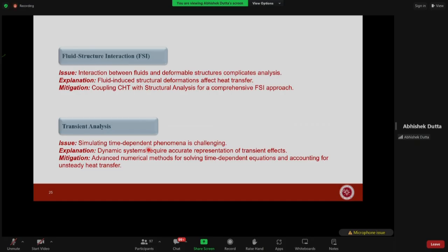The transient heat analysis. Yeah, this is also very important because most of the time our heat transfer solutions are steady state, and actually that is not accurate. So to avoid the mistake, we need to change to a time-dependent solution. And time-dependent solutions are actually very challenging. The general nature of transient is a very chaotic solution. You cannot understand whether you have reached your convergence or not, and these are really challenging. I myself have been facing this a lot, so I know these are big issues.